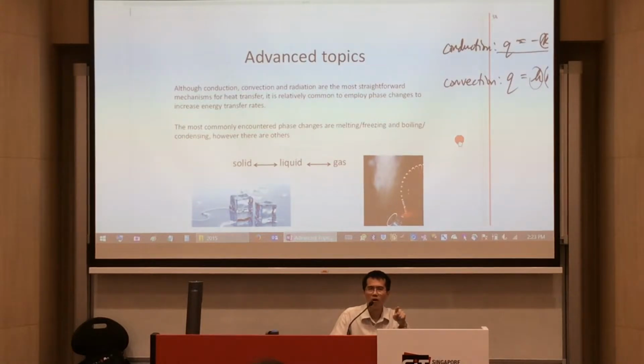So the part comes when we were talking about if it's on sea level, you have water that's boiling at 100 degrees Celsius and steam that can exist at 100 degrees Celsius. This change of state from liquid to gaseous state, both at 100 degrees Celsius, requires additional energy. How much energy? That energy is about 2,260 kilojoules per kilogram of water.